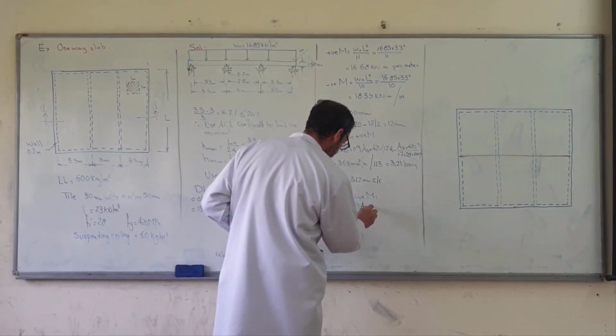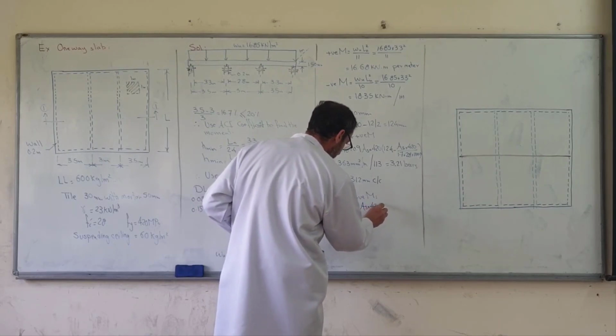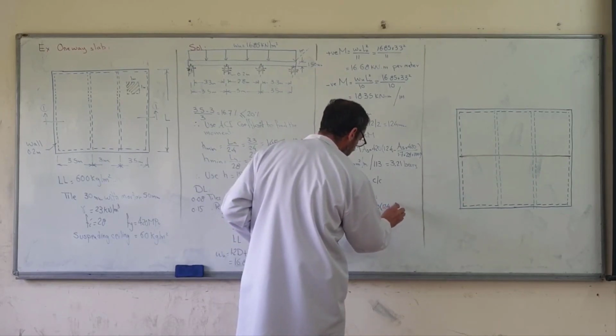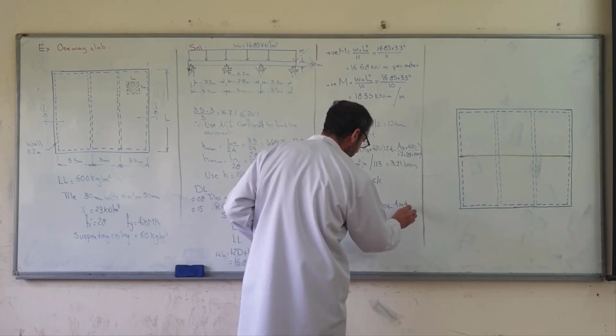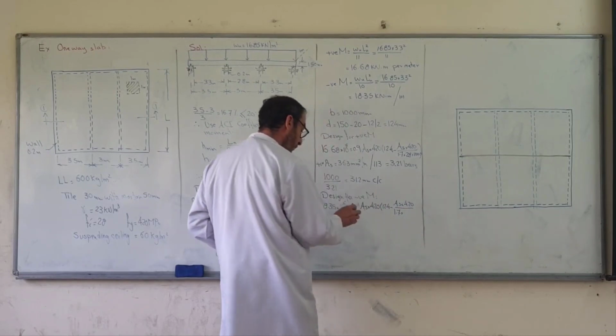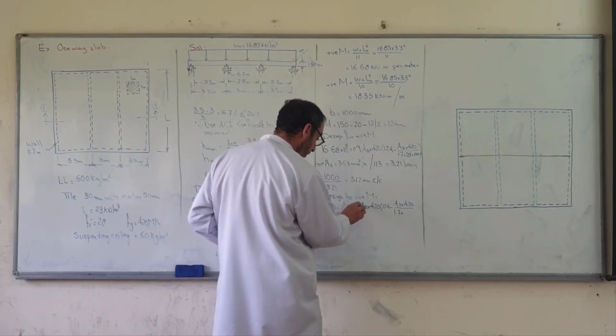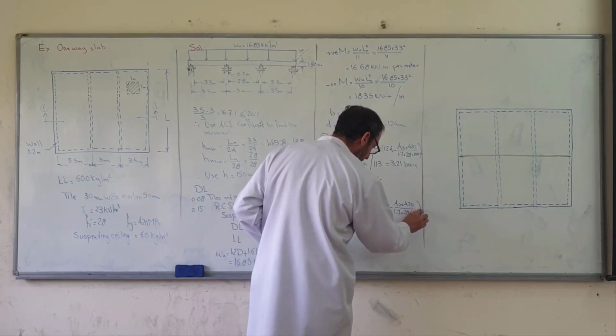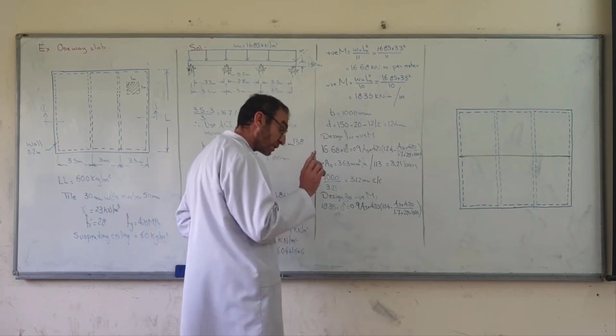As fy, d is equal to this, minus As fy over 1.7 f prime c. This is the simple equation of design for single reinforced beam, f prime c 28. Don't forget the width B is equal to 1,000.